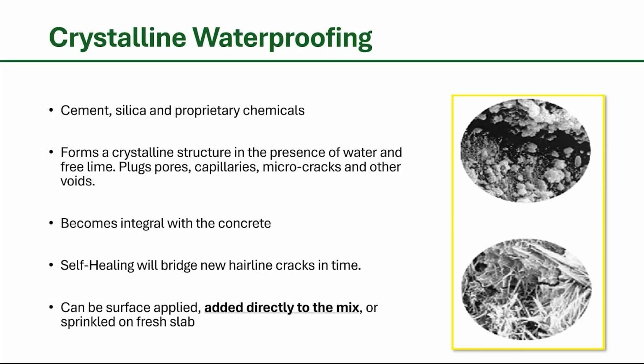It becomes integral with the slab. And the other wonderful thing about making it integral as an admix to the concrete is that you're going to have self-healing properties, because there's always going to be some unreacted calcium silicate hydrate in there that will bridge over and cause new crystals to form if there's a hairline crack and water intrusion.